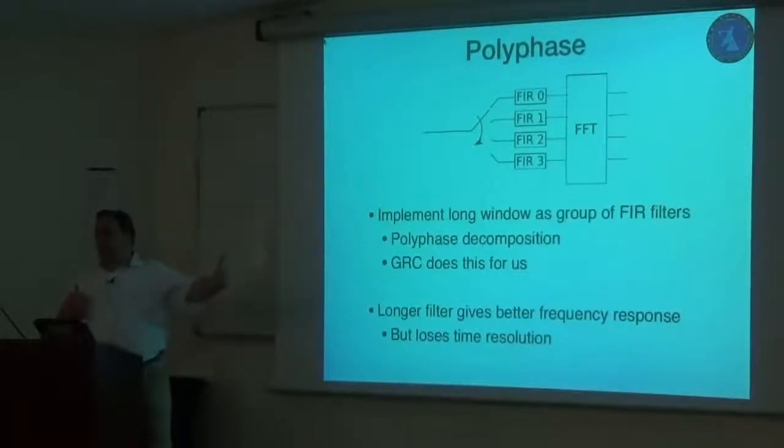So you take this very long sinc filter that you have, and that you actually want to do a smaller number of FFTs on, and this FIR filter has a particular length. So actually, if this filter has like 11 taps, and it rotates like that, that means that in fact you'll have 44 samples in here that actually determine the outcome of this FFT. That means I lose accuracy in the time domain. I don't actually know exactly where in this long term the particular thing happened, but I gain accuracy in the frequency domain, which in this particular application is more useful.